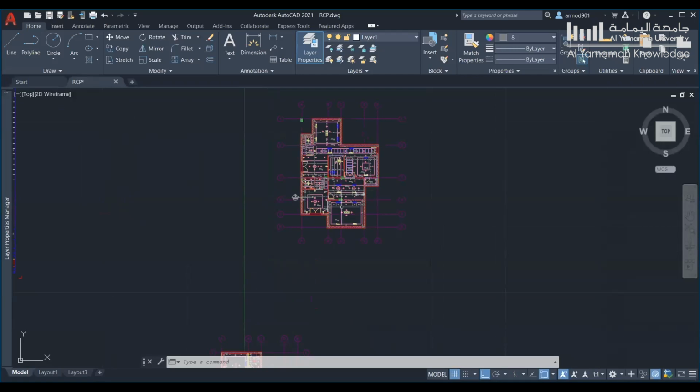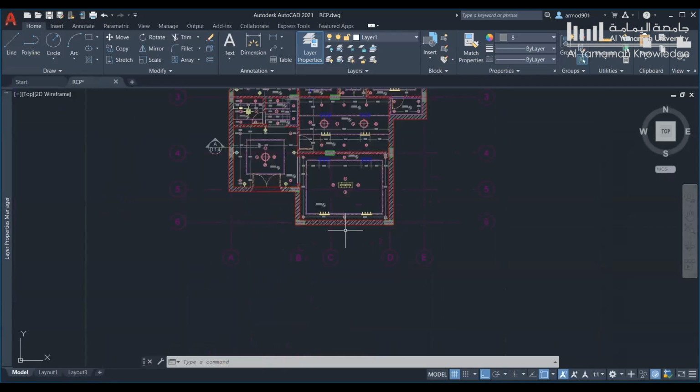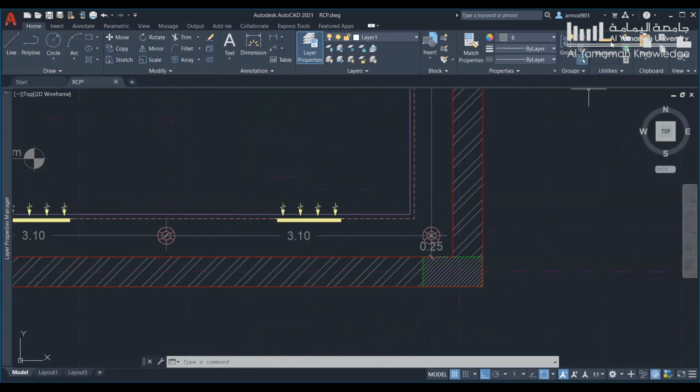Right now, the first step in exporting your work into a PDF file is basically to identify the unit, because you actually want to tell AutoCAD that you are using either millimeter or centimeter or meter. In my case, I am using meter, and a good way to know what type of units you're using is to measure the distance of the wall thickness. Since it's 0.35, that clearly indicates that it is in meters, because if it's in anything else, then the walls are extremely small.